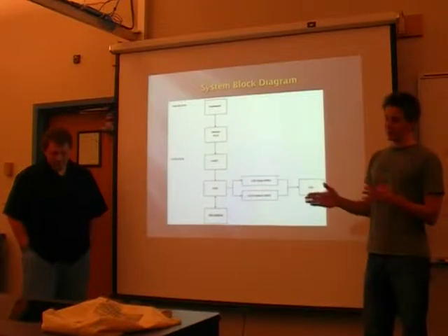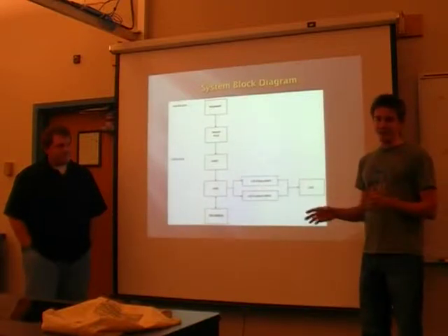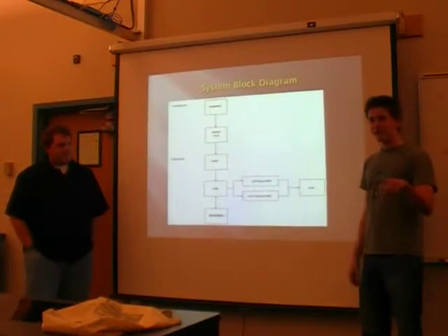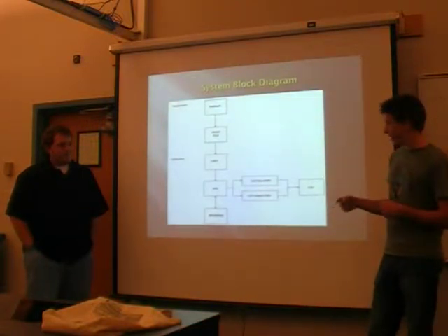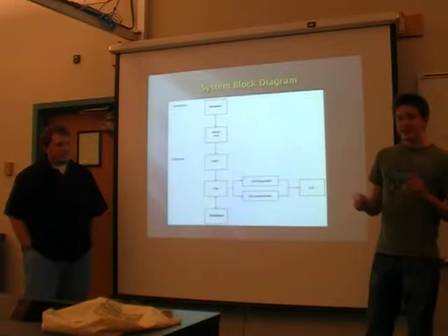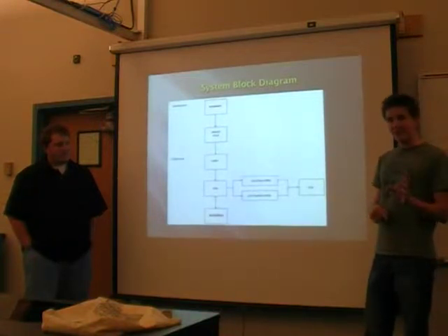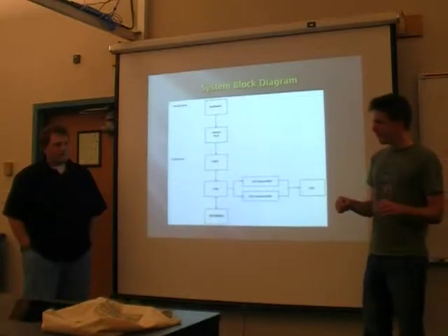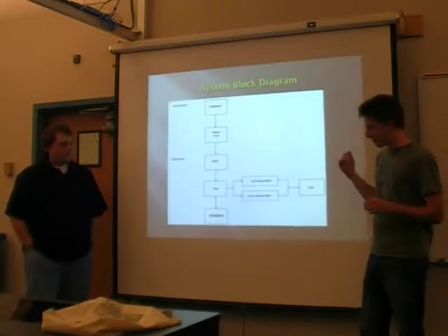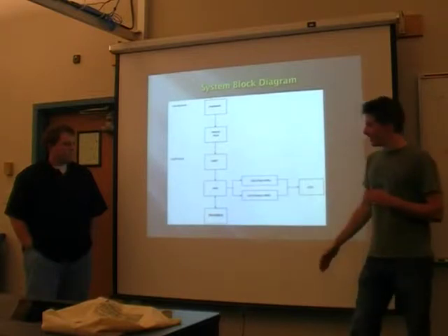And then you have to multiply that by 50 million, which is the clock frequency of the board, and that gives you a new clock rate that the UART operates at. The problem is that the number you get is only a rough estimation of the actual baud rate from the keyboard. I'll get to that later in the presentation.